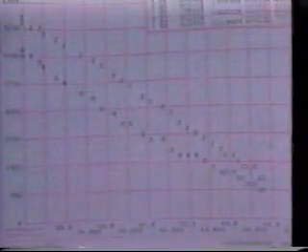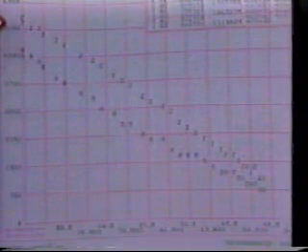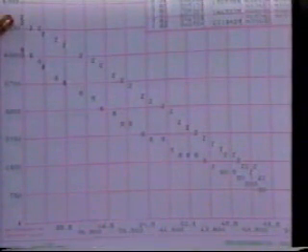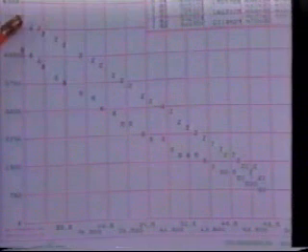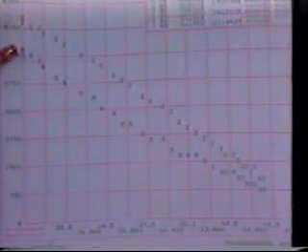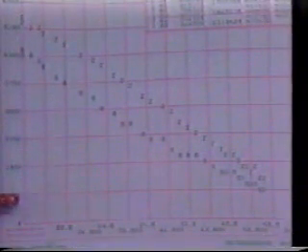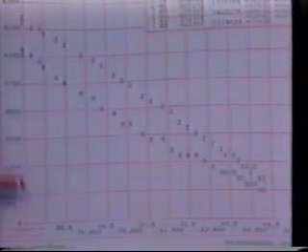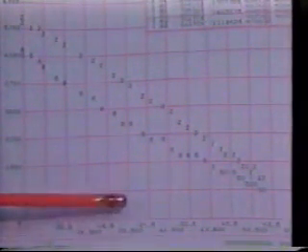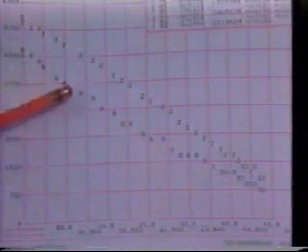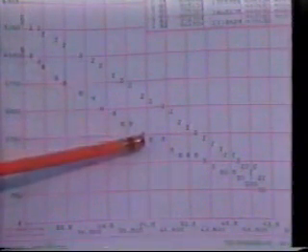The actual test dates are displayed with potentials, wellhead pressures, and bottom hole pressures over Z. We then take the tabular data and plot the information. We have 2 horizontal and 2 vertical scales. The first scale pertains to the pressure information. The Z represents bottom hole pressure over Z. The 0 represents wellhead shut-in pressure. The initial pressure would appear on the far side of the scale at 0 cum. The cumulative information is displayed on the bottom scale so that you can take the wellhead information and each test from initial test to last test is plotted.